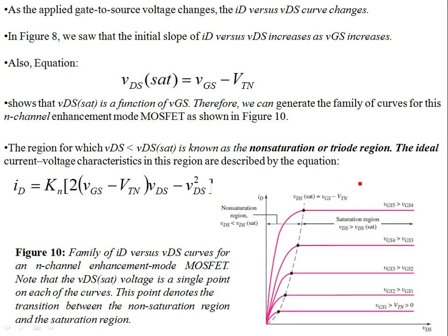In the fourth part of the MOSFET lecture, we talked about how you derive the current through the transistor, ID, given the drain voltage VDS and the gate voltage VGS. To turn on the transistor, VGS should be greater than the threshold voltage. If VGS is less than the threshold voltage VTN, the transistor is in cutoff, so you don't want that.